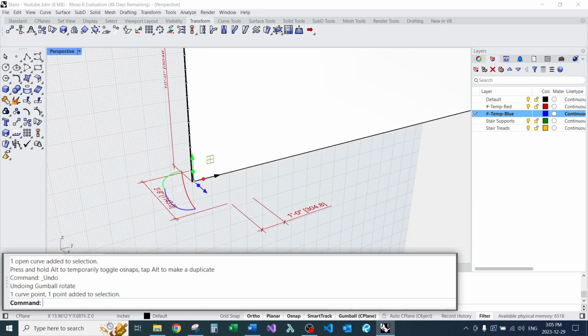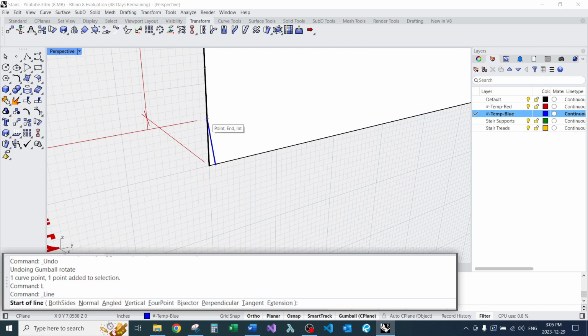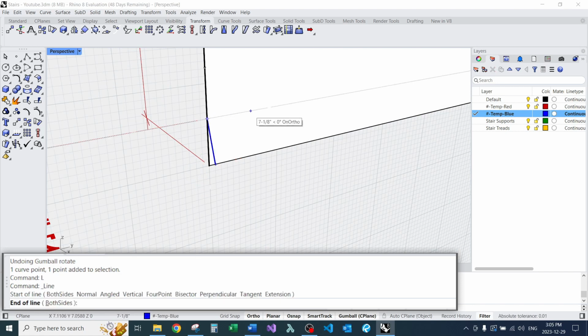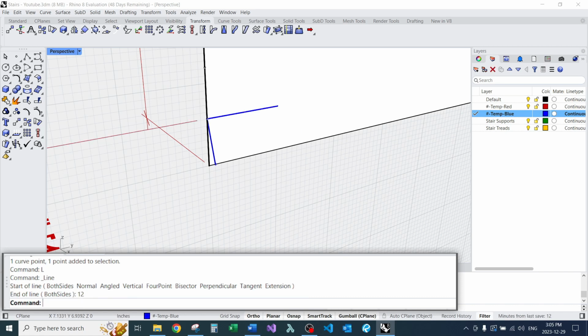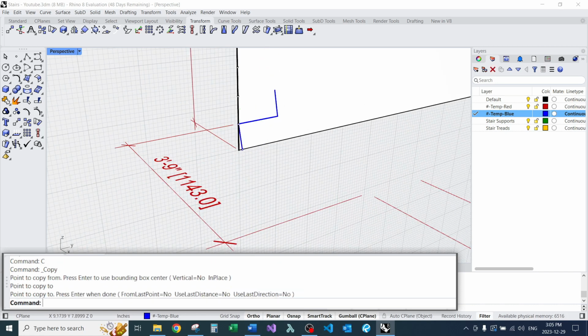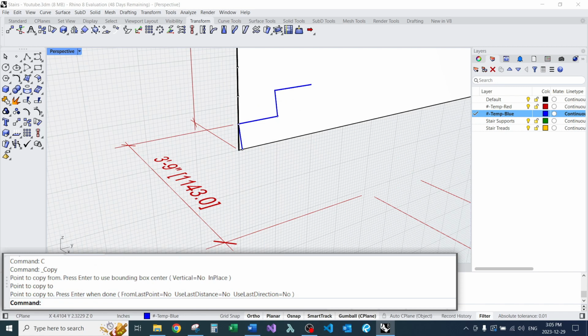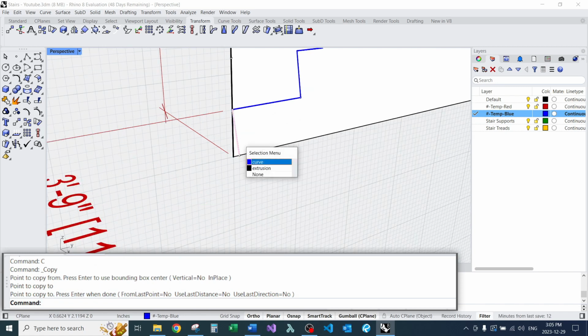And use a 1-inch nosing again. So I wanted 11-inch treads. This is a very common arrangement for concrete stairs. It's actually the most common. You always aim for 7-inch risers and 11-inch runs. And you only don't do that, at least where I am, if there's something in your way or you need extra clearance on a landing or something, headroom or whatever.